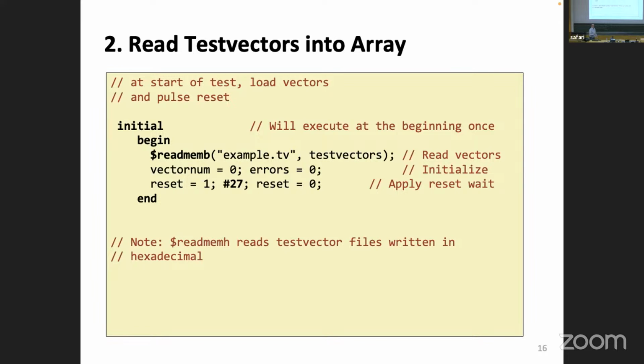We are coming into the reset exactly at 0. Yeah, that's no problem. At this point, the circuit is in an unknown state. You can't make it any worse. The reset is there to solve your issue. So the moment you pull the reset, the output will be at a known state. The point is, when you release it, the circuit will start functioning again. And before you let it function, just give it some space to breathe.